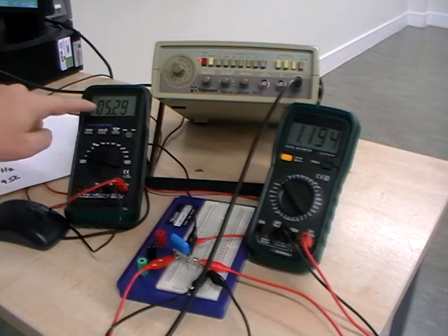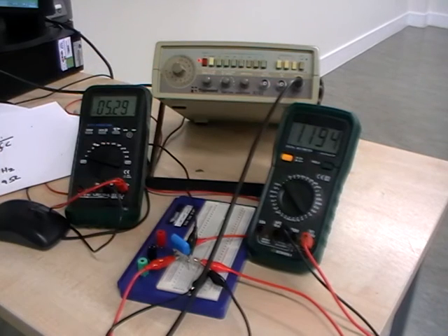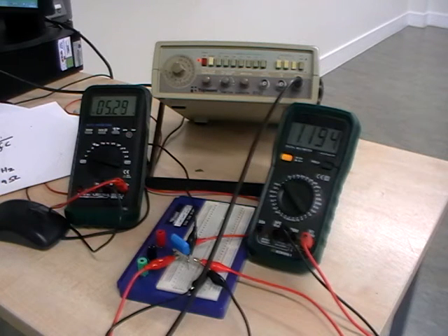Yeah? And at 200 hertz, we suddenly see we've got 5 volts across our capacitor, and we have got a little bit more than 1 volt across our resistor. And so we can see that suddenly it's only 5 times as high. So it's about maybe 700, 750 ohms across our capacitor. That's the reactance of our capacitor, dropping about 5 volts at 750 ohms or something. Round about there, roughly. So we are not too picky about the figures. It's all about the concept of what's happening when we expose our capacitor to frequency. And what you can see now is the reactance, the apparent resistance, drops down, goes right down.